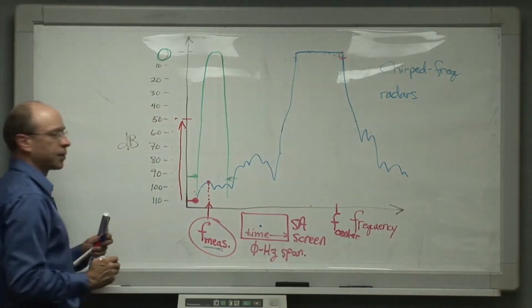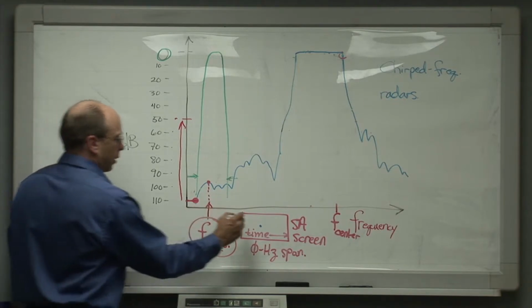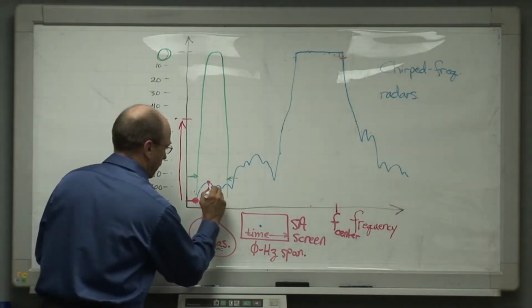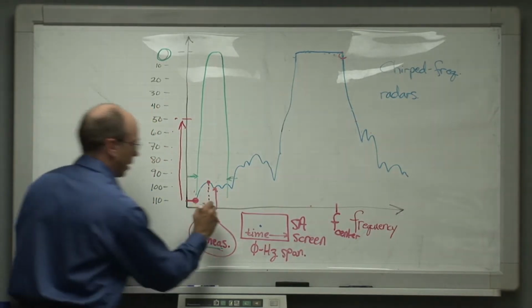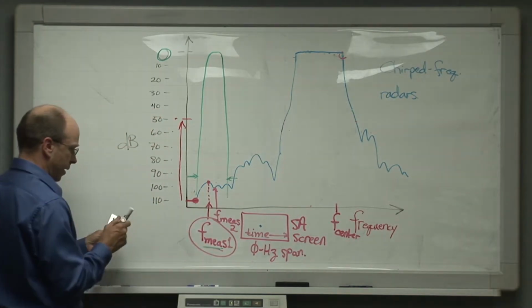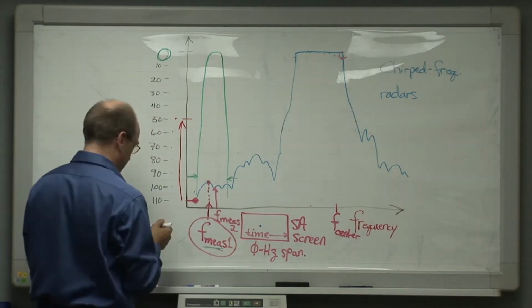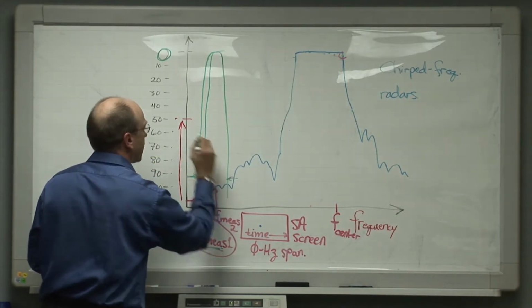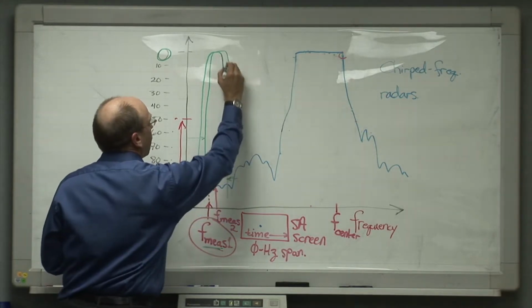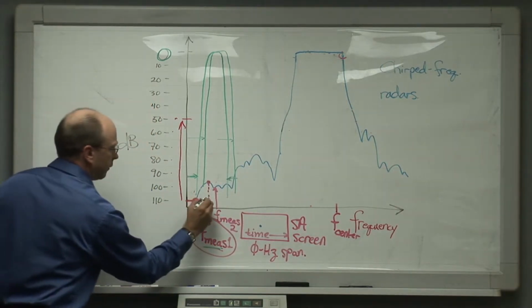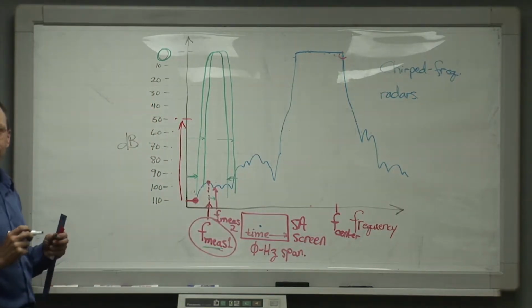which we do by waiting in time until the radar's done a complete beam scan, we'll talk more about this in a second. Then we move the measurement frequency up a little bit higher, we'll talk about how much higher in a minute, to the second measurement frequency, so this becomes FMES1, this becomes FMES2, and we move this bandpass filter sideways just a bit. We move the bandpass filter itself sideways by just the amount that we moved the tuned measurement frequency. So now you see what's happening.